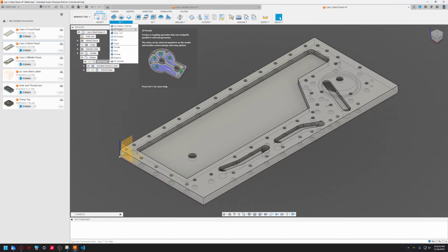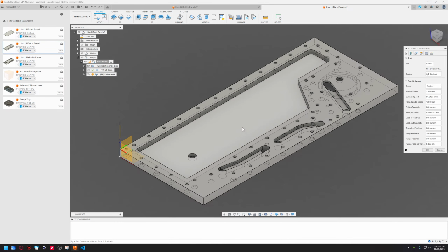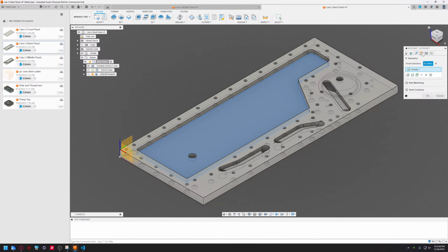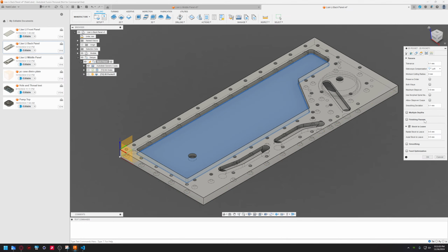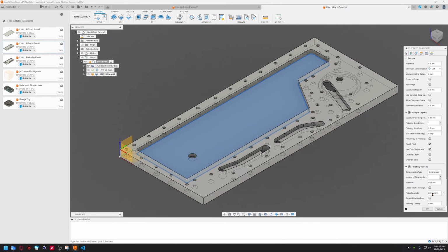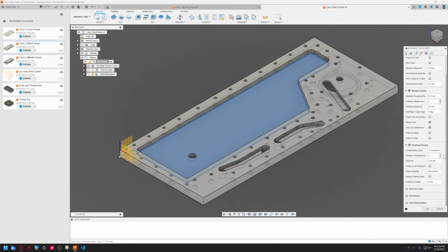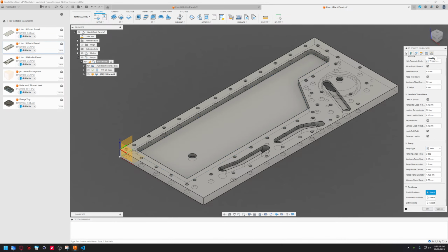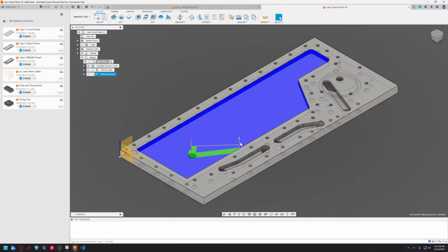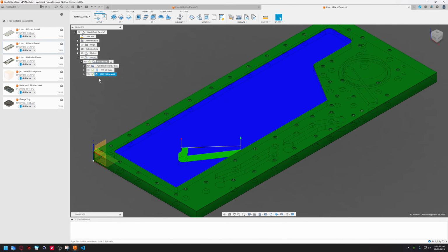The normal way that I used to do pocketing is, pocket like this, click here, one pocket selected, blah blah blah. You do the multiple depths. You can tell it to go one finishing step down, one finishing pass, no stock to leave, and ramp clearance is this. And if you click it, let's see.